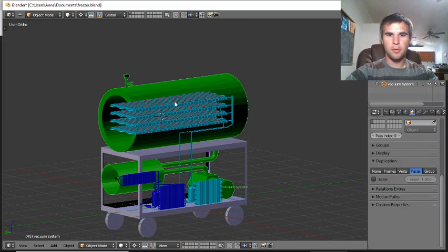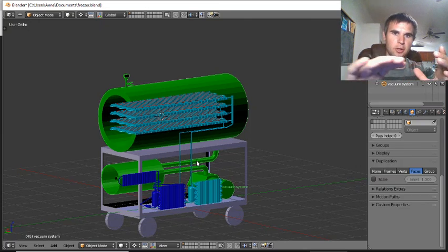So if you want to pull down the pressure within the chamber itself quickly and effectively, the tubing that connects the chamber to the vacuum needs to be as short as possible, and it needs to be as big in diameter as possible. Small diameter tubing, just the resistance from the friction of the material moving down the smaller diameter